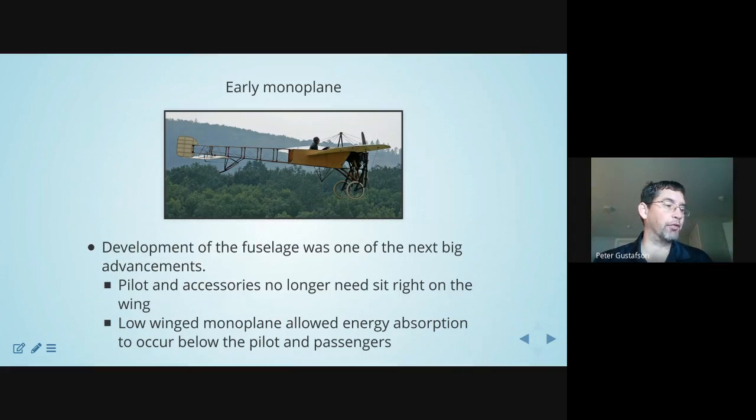Steve says lack of lift relative to the biplane. So you're right in a sense. Lack of lifting surface, Steve. It's comparatively less lifting surface, although of course that means ultimately you're either flying at higher dynamic pressures or flying with larger lift coefficients, and in each of those cases it has drag implications.